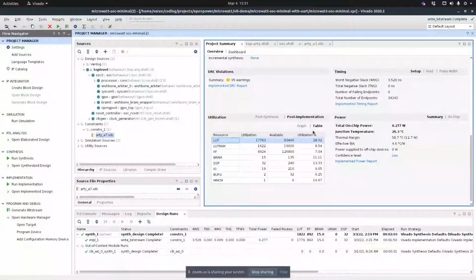You must switch off the use of the carry 4 block in Symbiflow, and likewise in NextPNR Xilinx, because it's to do with the resources of the way that the FPGA works. If you go above a carry of about 95 in length, it doesn't work. But there are options to switch that off, and then it will actually compile and work. Thank you, Ganesh. And yes, Symbiflow GitHub.io.